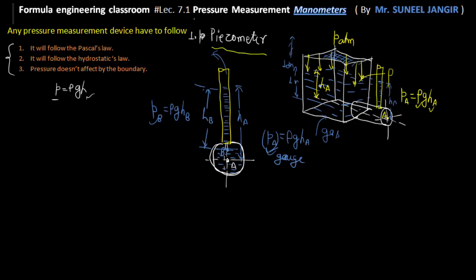When you attach this piezometric tube to this pipe, as the pressure in the pipe is less than atmosphere, and this end of the tube is open to atmosphere, which is higher than the pipe pressure, the air will rush in this tube.